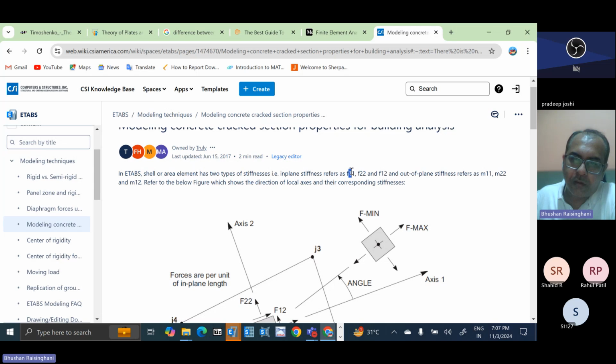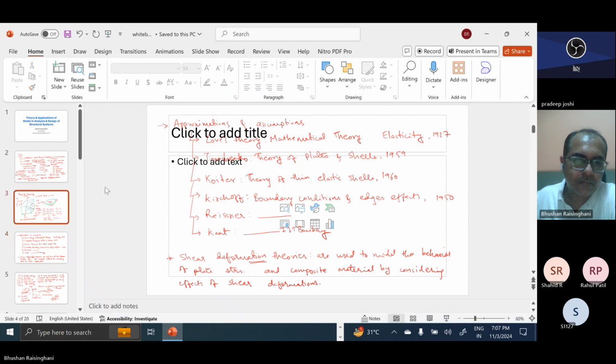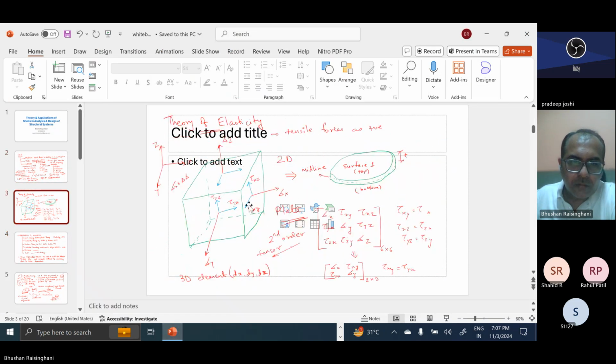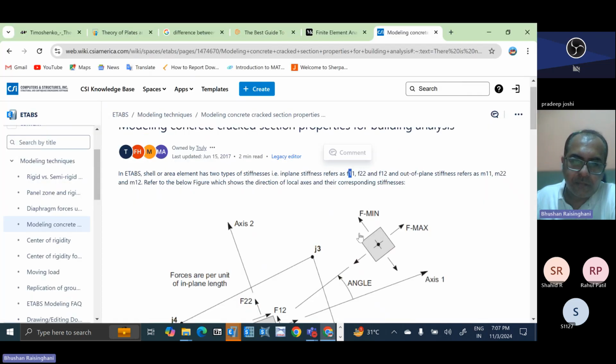First axis is your normal axis. I'll go again to the PPT. So sigma x, here you see the normal axis. For tau xy, x is the normal axis, and y is the direction in which the force is applied. Same, you have to apply it here. One is the normal axis on which the stress is being applied, and one is the direction in which the force is there. So this will be my sigma x.